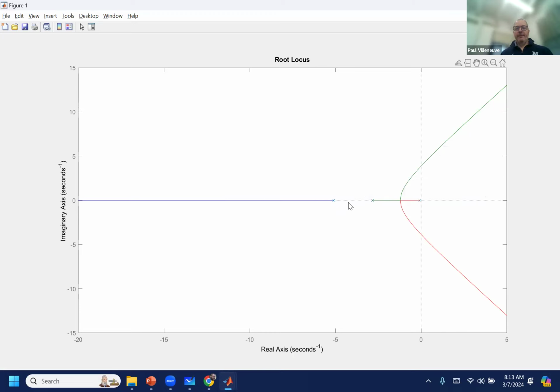Yeah, so if you want an outcome that lives somewhere between -5 and let's say -4, you can't get there from here. That system will never give you a pole. That's why it's blank over here. So depending on the gain, you can have poles anywhere else.